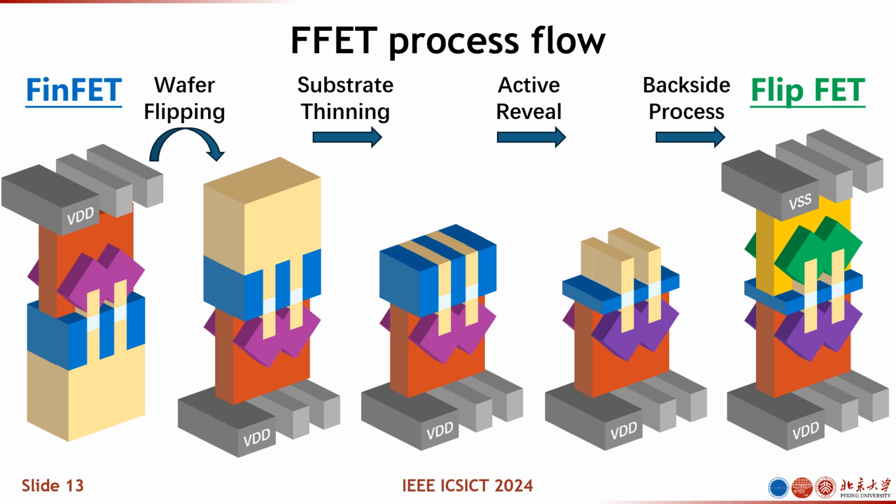So because of this, the top transistor and the bottom transistor are made on top of the same fin, and they are self-aligned. So you don't have any overlay problem because they are formed on the same thing. But the only difference is one is on the top part of the fin and the other one is on the bottom part of the fin. And the other thing, as you can see from the 3D cartoon, I also mentioned this before, that the top transistor and bottom transistor all have their individual interconnects, which is also symmetrical. And I will cover why this is important in the later discussions.